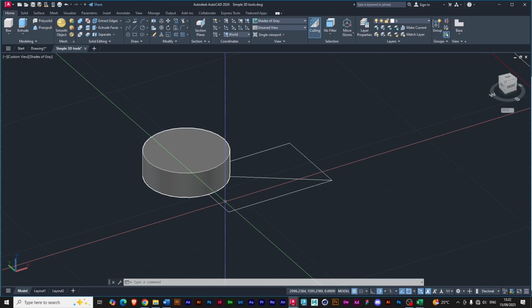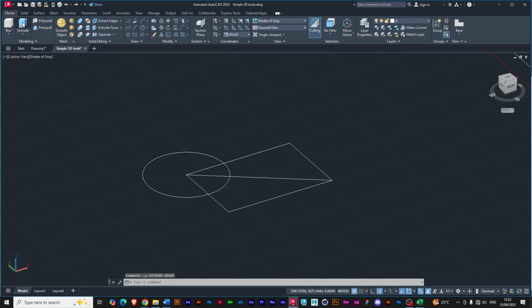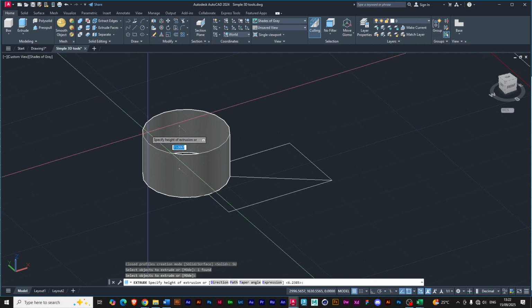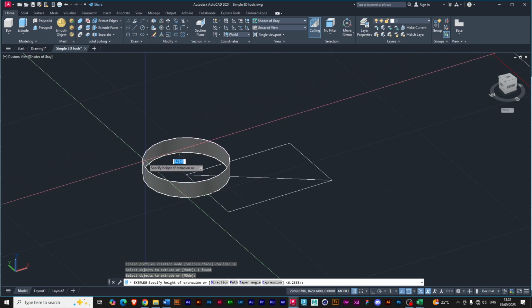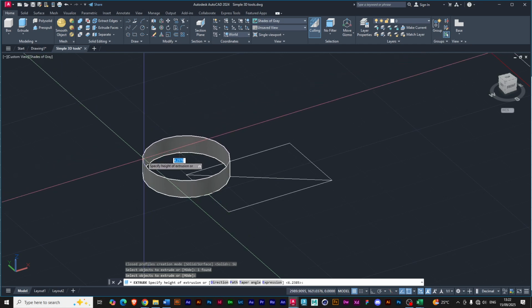It just marked that that whole circle has to be extruded. It doesn't pay attention to this. So if I did the extrude and change my mode to surface instead, pick the object and enter, it's going to extrude the surface from the lines, not the solid object itself.